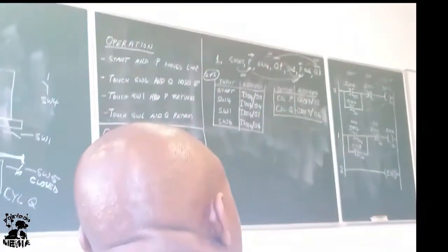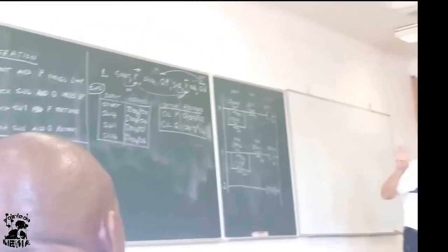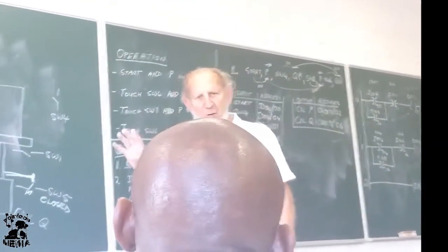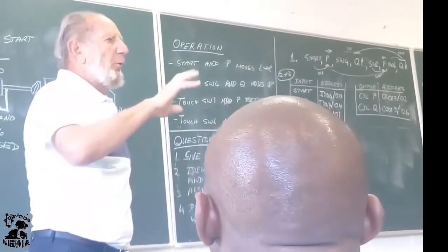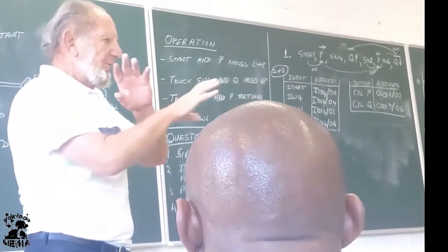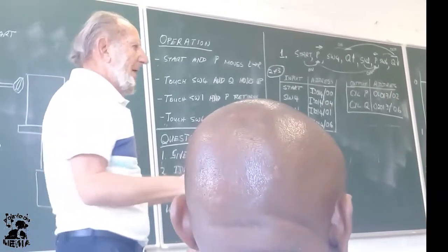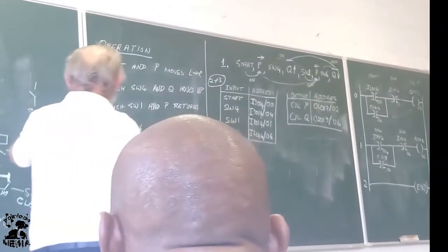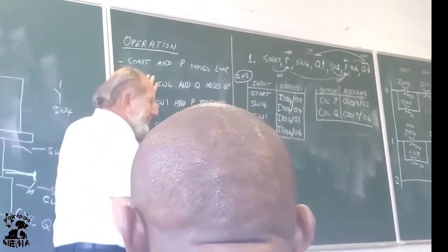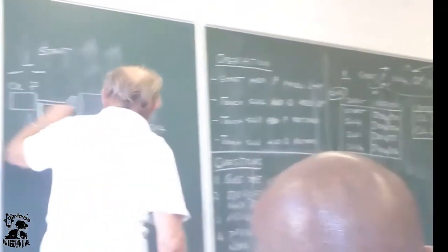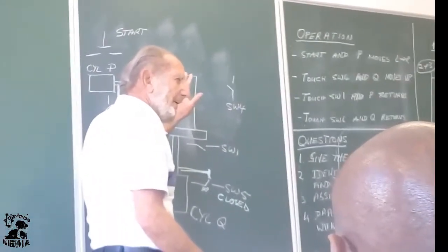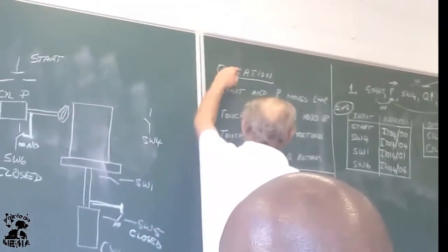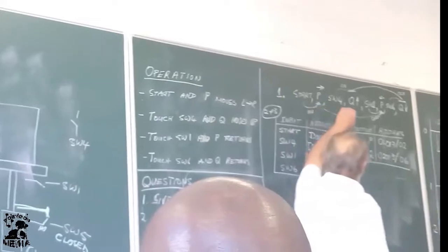People, we're going to do this 4 times. I've done it now for this machine. I will do it for the machine drilling 2 holes. And then I will do 1 or 2 with totally different drawings. It's important that you understand the machine and the operation. Check the operation if you can follow it on the machine. Check what is closed in the beginning. Then use the operation and write down the logic order.